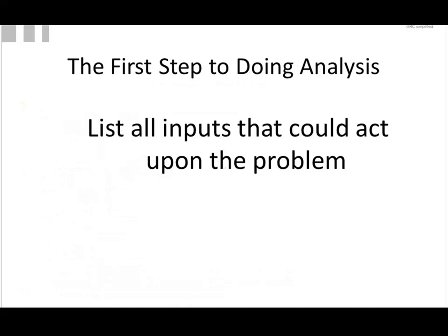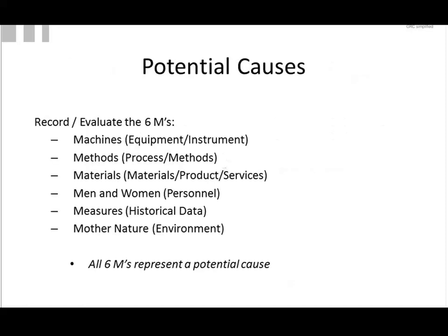Okay. Input analysis is important. The 2 tools for that primarily would be flow charts or process maps and the Ishikawa or cause and effect diagram. So let's look at the cause and effect diagram. I mentioned the 6 M's. That doesn't mean you have to tie it to 6 M's. You can use other terminology like I have in parentheses. It's nice. It looks neat if you want to use that, but there's no reason to do that. You can do whatever you want to. But generally, it's these 6 basic areas that are inputs to whatever manufacturing process you're dealing with.